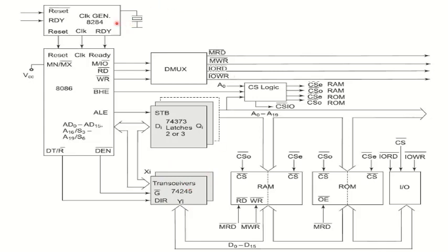And next is the clock. This is 8284 clock generator, and these are memory. So memory is basically used to store the data and program, and these are input output devices. And this is generating some signal, read write signal. This is chip select to select the chip, memory and input output devices. So basically this is providing the different controlling signals.